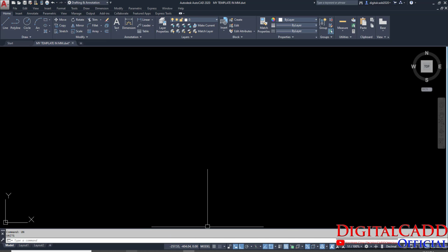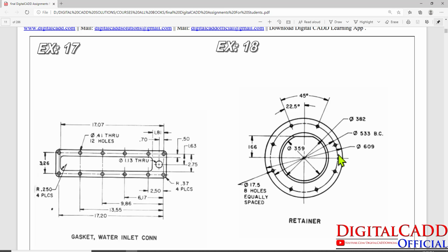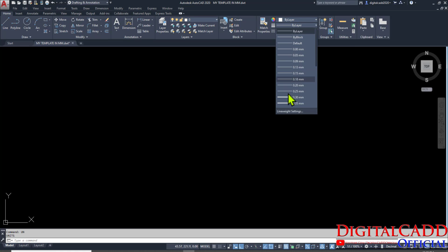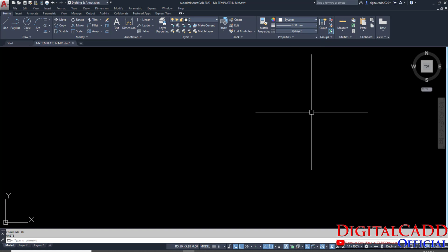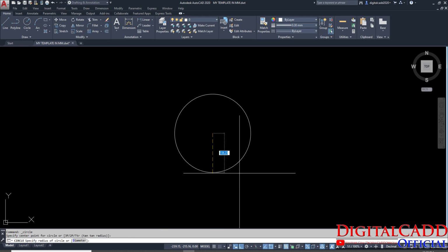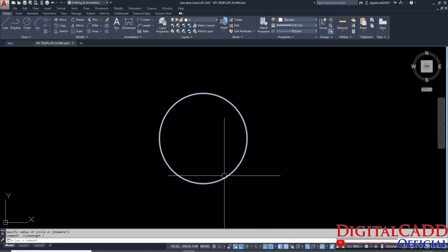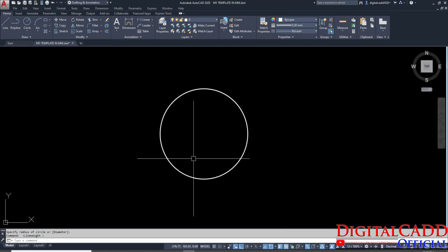First of all, you can see the drawing looks a little thicker and the dimension looks a little thinner. How do we set the line thickness? You know how to set it; here we have the option, and I always recommend doing this. Set 0.30 mm, and whatever you draw will continue with that thickness. If you can't see it, turn on the show/hide line weight button, so you can see the exact line weight applied to your drawings. So let's delete it.